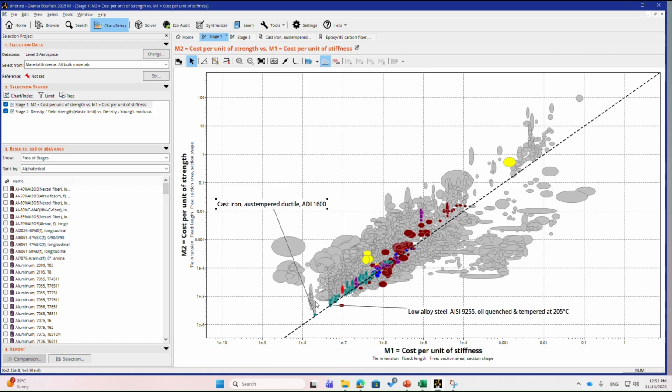That would be the case where you do not have a very high factor of safety, then you will be somewhere here with this coupling constant line. So I encourage you to go back and try these what-if scenarios as well and go through this whole case study. And I hope you are now convinced how much a simple, correctly set up material selection case study for your actual design can give you.